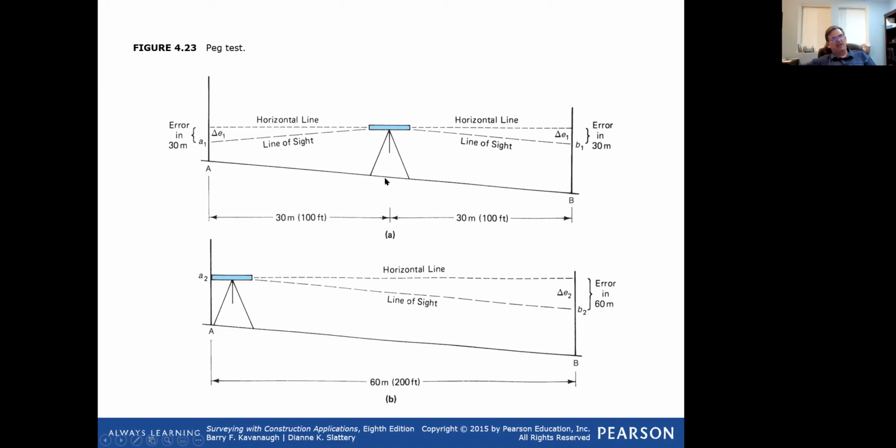You can just, again, pace there. It's one of the functions of pacing. You could do this whole exercise by pacing and just keeping yourself in the middle. You could go 100 steps, and then you keep this at the 50-step mark. Set 2 points on the ground. Take a reading over this one and get that answer. And then take a reading over here and get this answer.